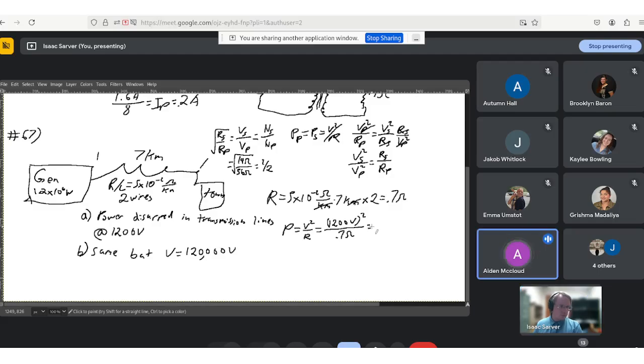Why is the resistance doubled when you have 2 wires instead of half? Because you would think that it would let it flow through twice as much. The thing is that it would go out through the one wire and then it has to come back through a different wire. Oh, okay. So it's not sending 2 wires the same way.